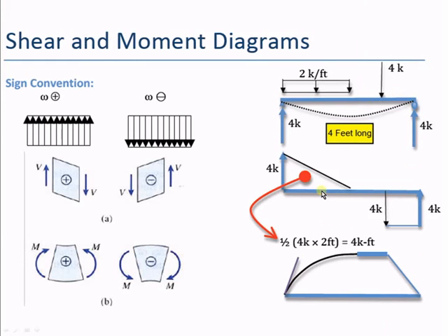Okay. So to summarize, this is our sign convention that we're using, and you saw that on the first page. So when we're developing those formulas, if we keep this sign convention while we develop shear and moment diagrams and using our loading diagrams, these will all be consistent. In fact, you can continue to integrate, divide this by EI, integrate it again to get rotation, integrate it one more time to get deflection, and it'll all be consistent with each other.